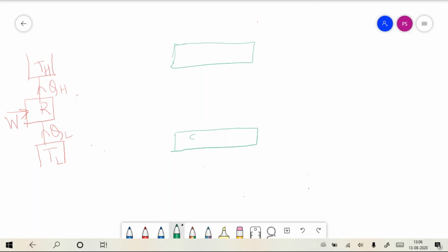Okay, so this is a heat exchanger, the evaporator. And there is another heat exchanger which is the condenser. The working fluid in the refrigeration system is known as a refrigerant. So what happens is, in the evaporator there is a transfer of heat from the space to be cooled. For example, if this is your space where you are storing your vegetables or some goods which are to be preserved.